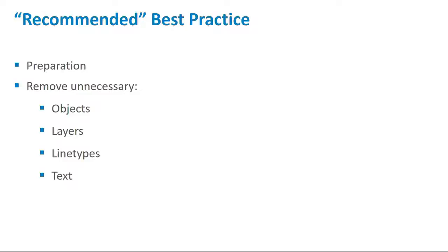Good point. Fernando just said if you are doing that editing process within AutoCAD, make sure that the properties for everything are by layer. Not changing the colour of something or the line type of something. If you want the properties to stay, make sure it's all by layer. Good one. Yeah, so then you could potentially, if you wanted to, change that layer in Revit to another line type.